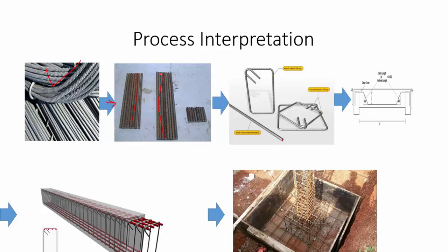Okay, for example, if we have a footing, this is the footing, and this footing has a size. If we say this footing has 2 meter by 2 meter size, what we will do, this steel bar, one steel bar is 12 meters. So you can see this is the higher length. So what we will do, we will just cut this steel bar into pieces like this, 2 meter, 2 meter. However much we need, we simply cut from this full length of the steel bar.